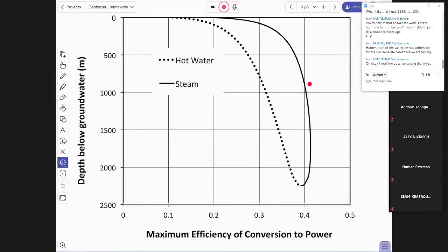And so the place I'm looking here, again, is the maximum they've been able to do for steam injection. The scale of the system that I'm looking at is something in the range of 1 million cubic yards. Again, I'm looking for grid scale energy storage. So if I have something on that scale, these calculations show that I could push something close to 100 megawatt power capacity. And you can run that 24/7, because what you're doing is taking half that energy during the day, putting it underground, taking the other half of that energy and putting it through your power system.